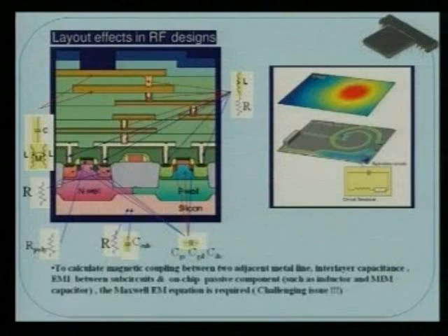But those vias can be modeled, as I say, when the frequency is high and the wavelength is comparable to the size, you cannot take the lumped parameter model, you have to take the parasitics. So that is inductor and resistance. So simple vias are not simple resistances, but they have an inductor too.